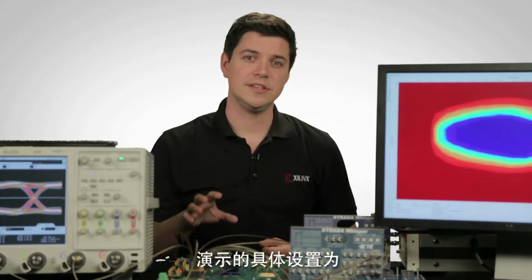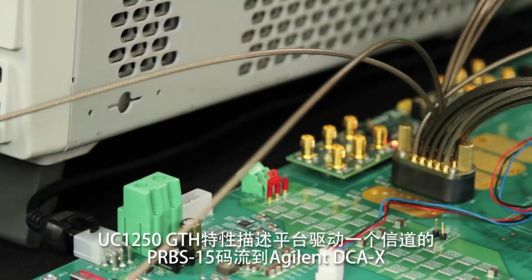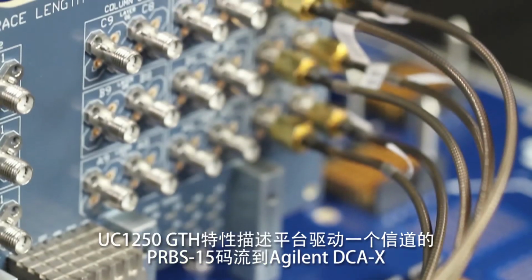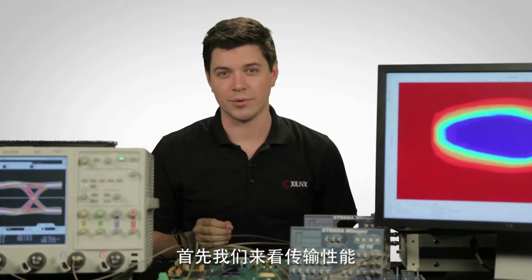This setup includes the UC1250 GTH characterization platform with the Kintex UltraScale KU040 device, driving one lane of PRBS15 into the Agilent DCA-X and another 3 lanes running PRBS31 through 30 inches of backplane. First, let's talk about transmit performance.